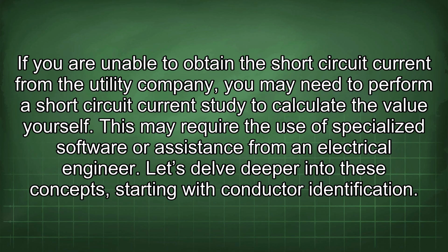If you are unable to obtain the short circuit current from the utility company, you may need to perform a short circuit current study to calculate the value yourself. This may require the use of specialized software or assistance from an electrical engineer. Let's delve deeper into these concepts, starting with conductor identification.